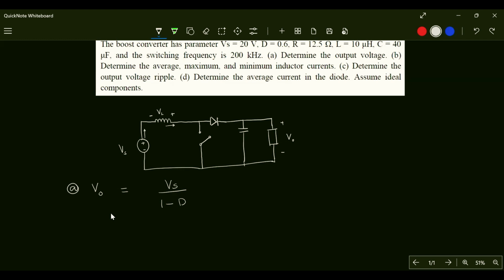As you can see, duty cycle is always less than 1, okay? So this term, the denominator, will always be less than 1, isn't it? And you know that when you divide a number by a number less than 1, the overall outcome is that the whole fraction will increase, right? In short, when you reduce the denominator, the whole fraction goes up. So this voltage here is being multiplied by a number greater than 1, in simpler terms, so the voltage will increase.